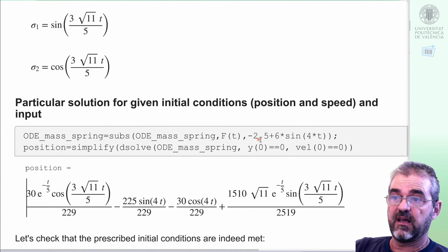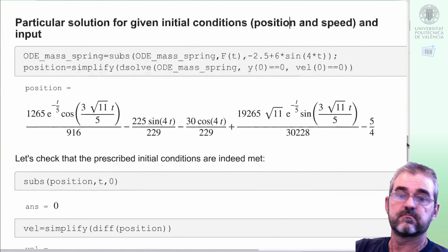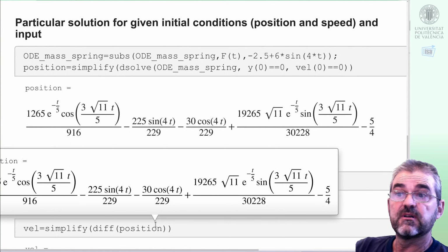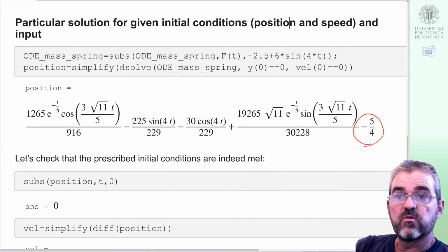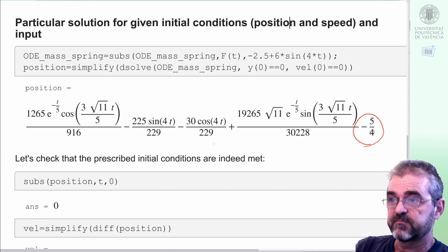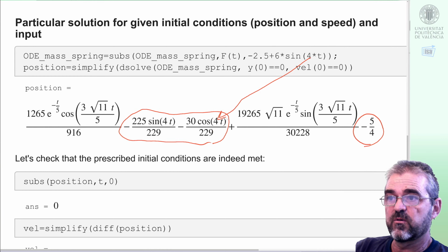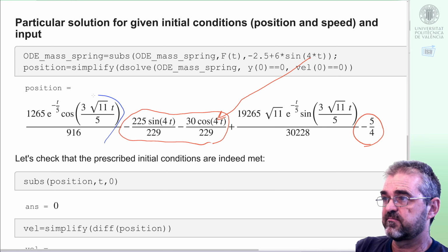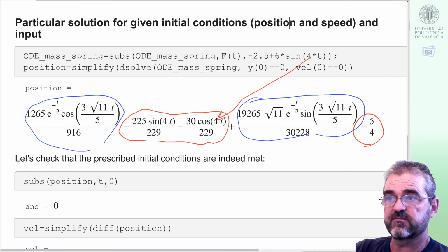We can now add both components, the constant and the external vibration, and in this case we have what is called superposition, in the sense that we get the new constant equilibrium we saw before, the steady state stationary sinusoidal response, not damped, with this 4 radians per second of angular frequency, and we get the decaying exponentials from the initial free response.